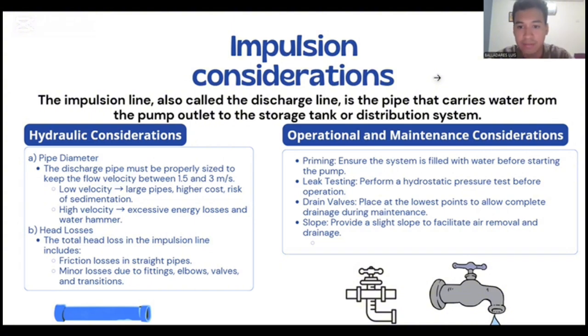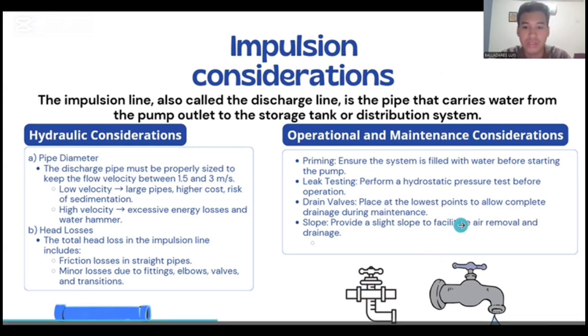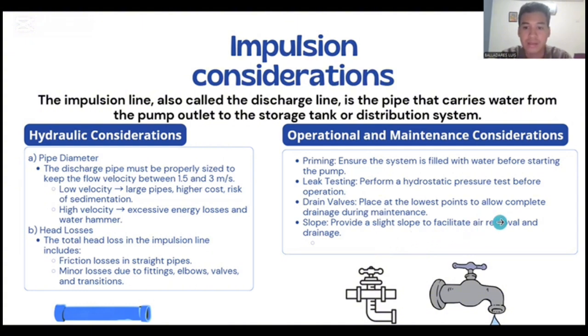Also, for leak testing, perform a hydrostatic pressure test before operation. A drain valve is placed at the lowest point to allow complete drainage during maintenance. And finally, slope: providing a slight slope to facilitate air removal and drainage.